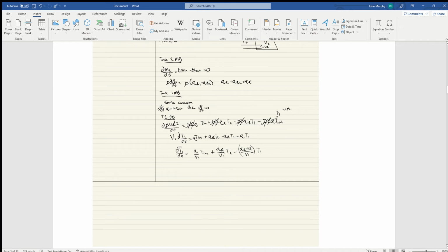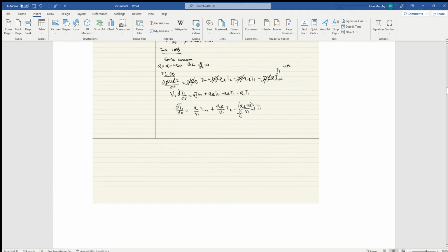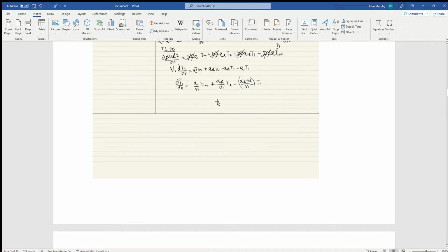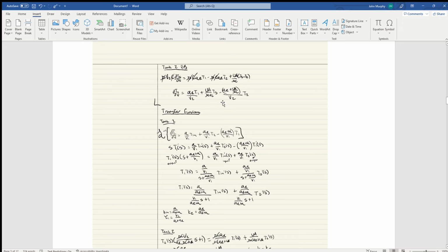First off, we want to start with the mass balances and establish that QR is going to be equal all across the recycled volumetric flow, and the Q is going to be equal in and out. Basically, there's no accumulation or loss of liquid. Continuing off of that, we have the energy balances, which make us solve for dT1/dt and dT2/dt, as listed right here, just doing in minus out and accumulation, but there's not really accumulation.